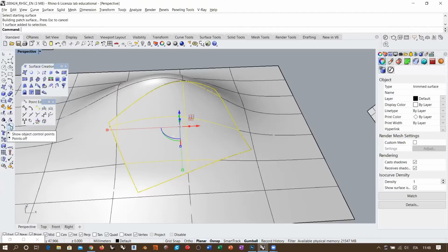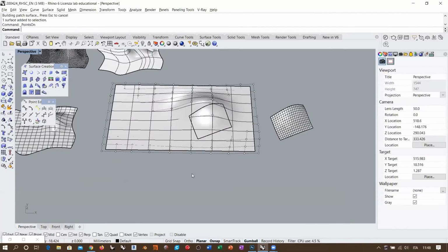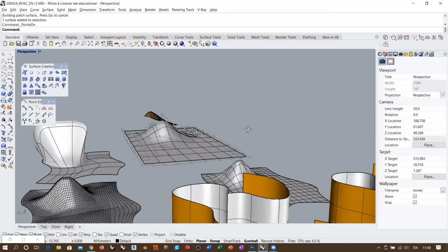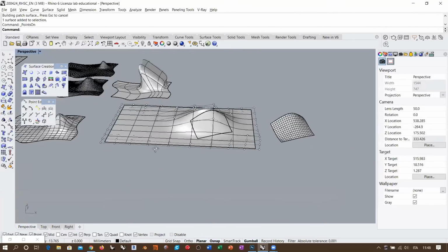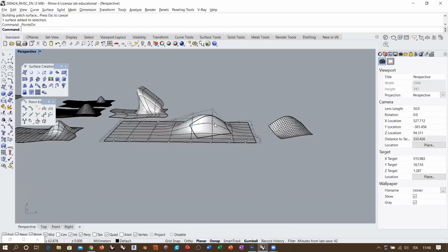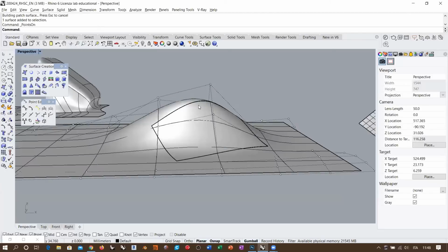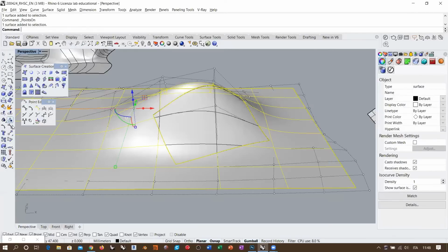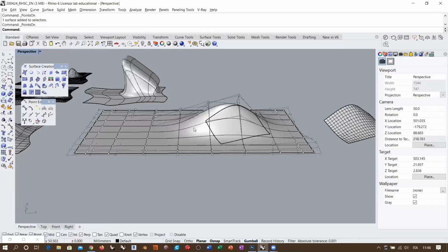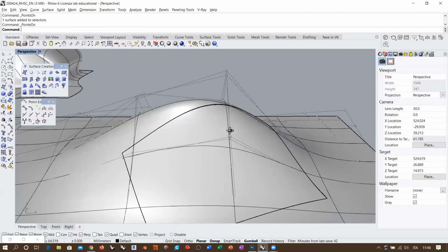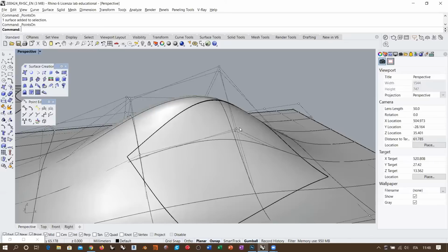And if I activate a control point, look at what we got here. This is exactly, or well, not exactly, but it's the topology of the patch that corresponds exactly to the extension of the surface that we selected as starting surface. So we see that basically, if I select also this one here and activate its control points, you see that there is a whole part of the surface which has the same identical topology, but you also see that there is some deviation between the topology of the actual patch and the original surface. So this patch is not rebuilding the original surface, it's a patch, okay?